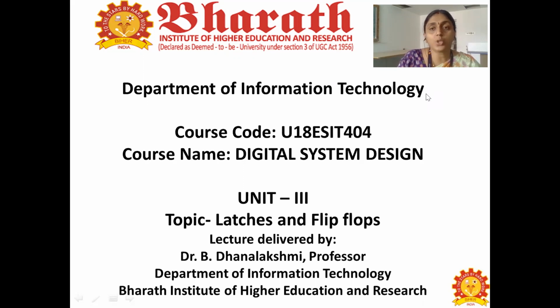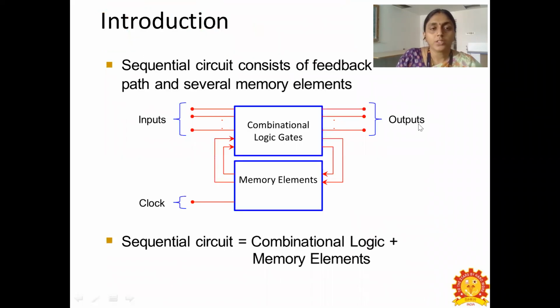Today we will see the topic in Unit 3, Latches and Flip-flops. First we will see the introduction about sequential circuit. A sequential circuit consists of a feedback path and memory elements. Compared to the combinational circuit, we have a memory element here in addition to the other gates. The sequential circuit comprises combinational logic gates and memory elements.